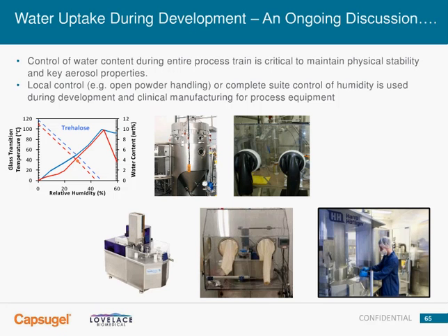Likewise, as we hit on again and again, water content. Certainly during encapsulation it's equally important. We don't want to ruin the product during that last step in the manufacturing process. So what's shown here is local control for small units like the Excipient in the middle bottom picture, or with the larger units. Local control is certainly possible, but usually at some point you just need to go to a full suite control. So in the suite that's installed, shown in the lower right, we can control the entire suite down to less than 10% RH for the really hygroscopic formulations.